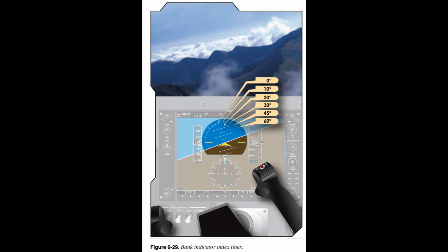As experience increases, pilots begin to know approximately how much change in throttle position is required to produce the desired change in airspeed. Different aircraft demand differing amounts of throttle change to produce specific performance. It is imperative that the pilot make the specific changes on the power instruments and allow the performance to stabilize. Avoid the tendency to over-control. One common error encountered with glass panel displays is associated with the precision of the digital readouts. This precision causes pilots to focus too much attention on establishing the exact power setting.